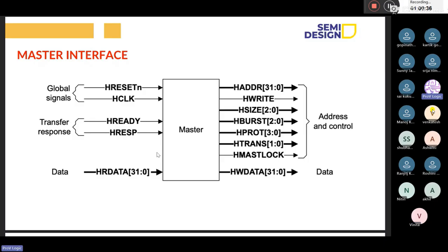But if you go to the AXI protocol, there we don't have just a few signals like that. We have different channels: write channel, read channel, response channel. Based on the channels, we have the separate names. Suppose write address, write data, read data. According to that, we will have names like AW, W, or B response, based on the channels. Only in the APB protocol and AHB protocol it will be represented with P and H.